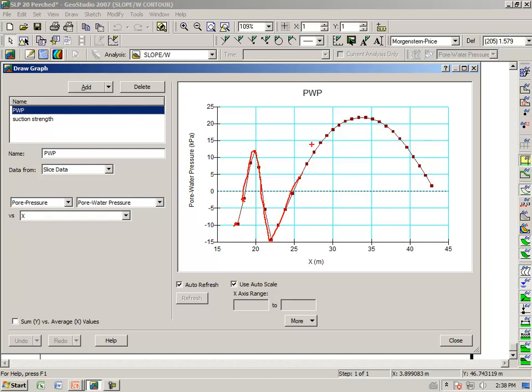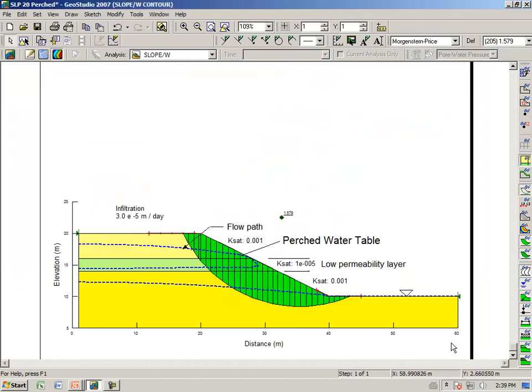As I have already said, a pore pressure distribution like this is not possible to describe with a piezometric line, and something like a SEEP/W analysis is required for this case. It could be done with a spatial variation or a spatial function of pore pressure head specified, but in all likelihood, for you to know where the perched water table is, you would have done a SEEP/W analysis anyway, so you might as well use the SEEP/W results in SLOPE/W.